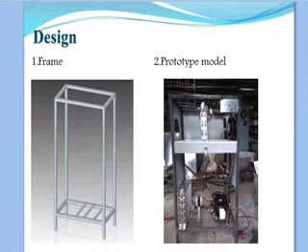So in our project, we have used a gas compressor. Then the next is the evaporator. It converts the liquid form of the chemical substance into vapor. Then we have the condenser. It's a heat exchanging section to cool down and condense the incoming refrigerant vapor into liquid.